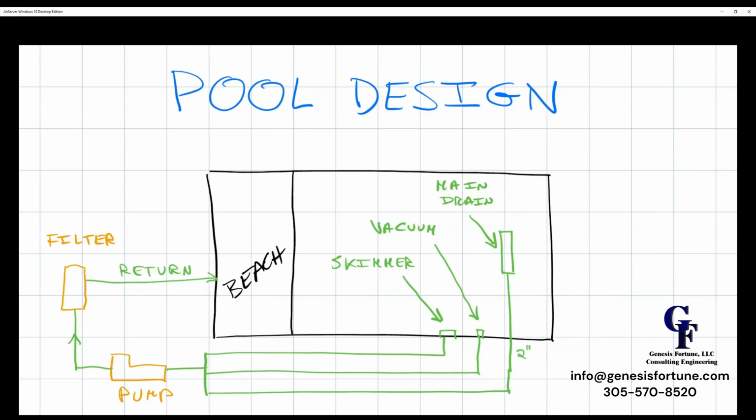The pump will be absorbing depending on certain valves that your pool plumbing contractor will have to set on these lines. It will absorb more or less from each line going into the pump, and then from the pump, as I said, goes through the filter and going back into the pool. So the main drain, once more, is just absorbing water from the deepest side of the pool.